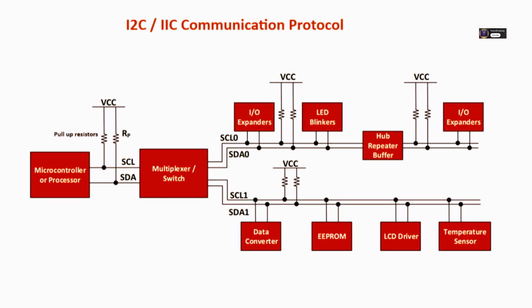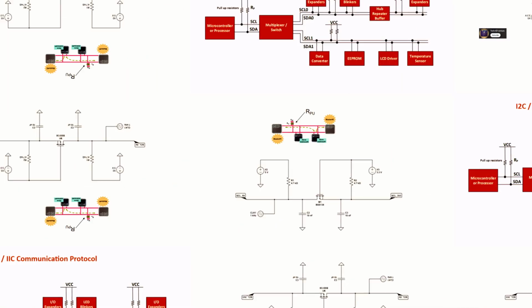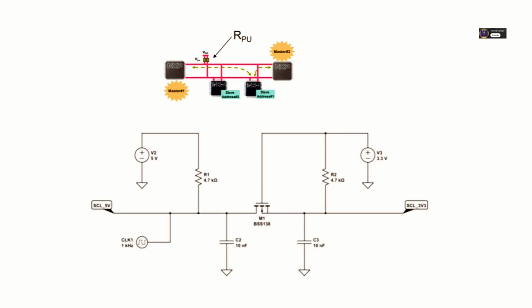And what about voltage levels? You often have chips running at different voltages on the same board, right? Like a 5V microcontroller talking to a 3.3V sensor. How do you handle that safely? Very common issue and crucial to handle correctly. You absolutely cannot just connect them directly if the voltages differ significantly. You'll likely damage the lower voltage device.